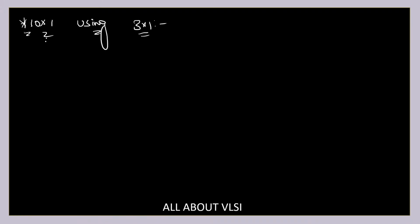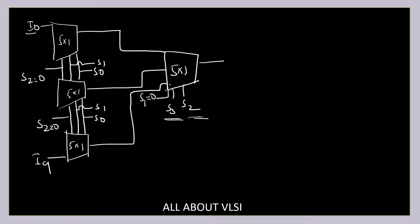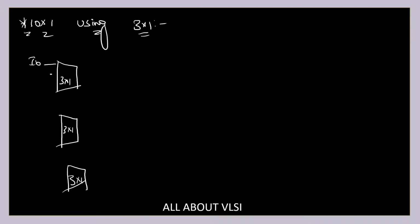So I'm going to have 3 cross 1 multiplexers like this. This is 3 cross 1, 3 cross 1 and 3 cross 1. I'm going to have I0, I1 and I2 connected, then I3, I4 and I5, and I6, I7 and I8.